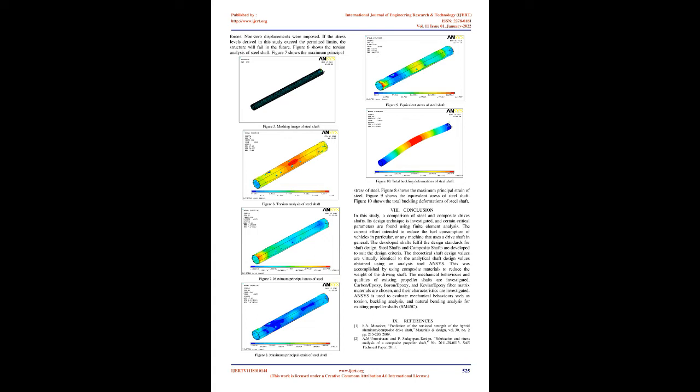The aforesaid characteristics of composite materials are used to fabricate the mechanical drive shaft using a composite combination of a glass fiber CSM, 0%, 10%, 20%, 30%, 40%, 50%, and IPN resins, and the shaft is experimentally tested using a torsional testing machine. A comparable shaft is modeled in CATIA V5, and numerical analysis is done in Ansys to cross-check the experimental data. Finally, the optimal range for mixing e-glass fiber with IPN resins is identified.